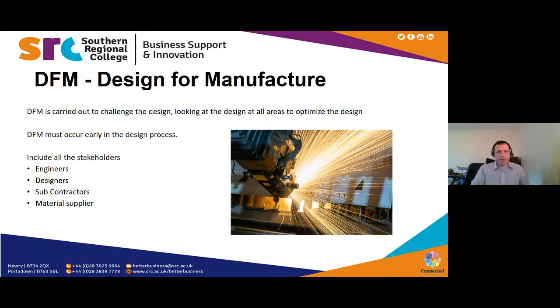DFM occurs early in the design process because the later you leave it, the more expensive it is to go back and improve it. For example, in the car industry, once they recall a car, after 10,000 have already been sold, it's a very expensive and long-winded process.